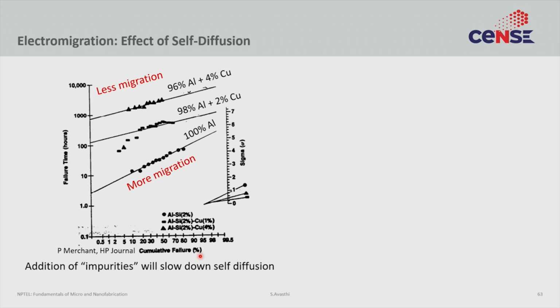So, what you would do is you would test 1000 devices and you would plot at what point they failed, and you can then plot a cumulative figure, right. So, you would start seeing failure at some time, and then as more and more devices failed, you would accumulate the failure rates and ultimately reach 1. And so, what this curve is trying to tell you is the rate at which the migration is occurring.